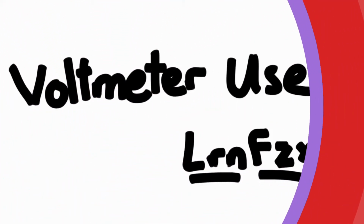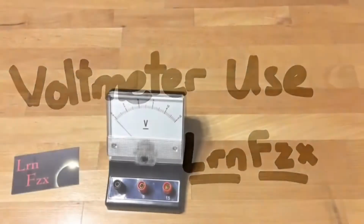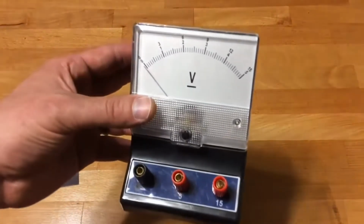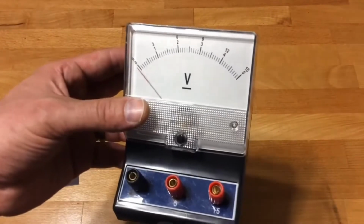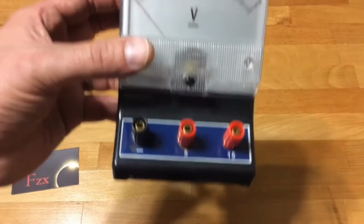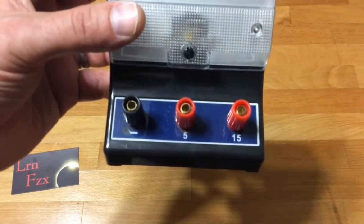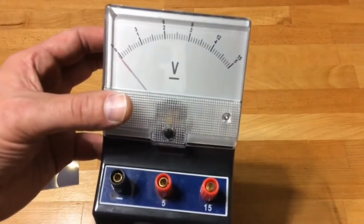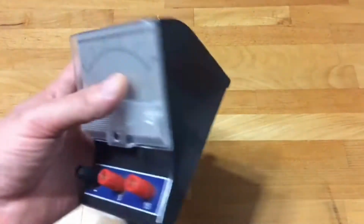Use a voltmeter. The instructions work for any meter, but this is the one that we use here in class. The big fat V says voltmeter. Notice there are two ranges, the upper range to 15, the lower range to 5, and the connector is down at the bottom. The black one is negative, and there are two positives, one for the 5 volt range at the bottom, one for the 15 volt range.